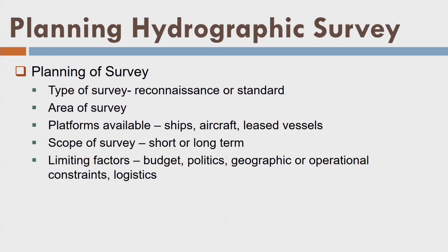How to plan the hydrographic surveys? First of all, we go for the reconnaissance survey. We should know what is the area of the survey, which is like say kilometer square, and then platforms available like we have ships, aircraft or vessels. Then whether it's a short term or long term survey. Long term means I will collect the data after a certain period which is quite long, and short term means I am frequently taking the data. Then other limiting factors like budgets, political reasons, geographic or operational constraints and logistics are factors we should consider in the planning part of the hydrographic survey.